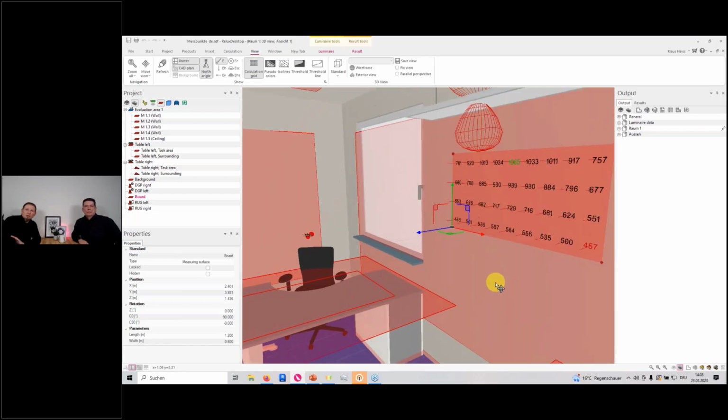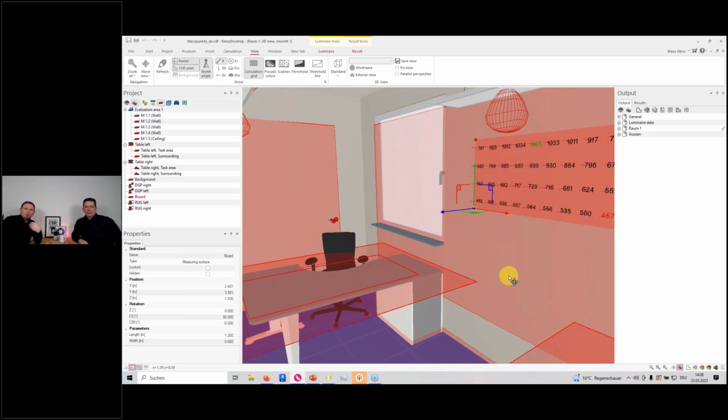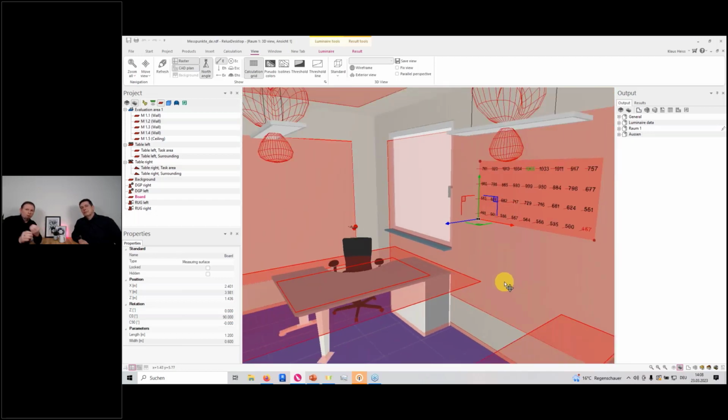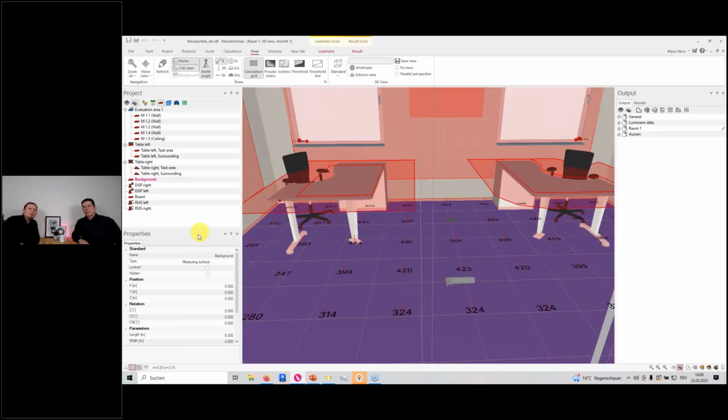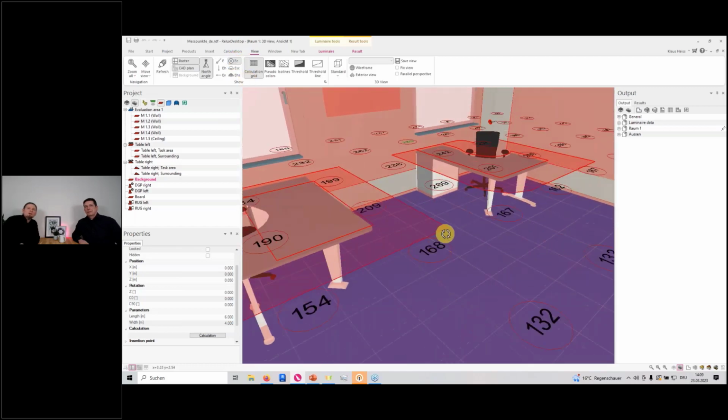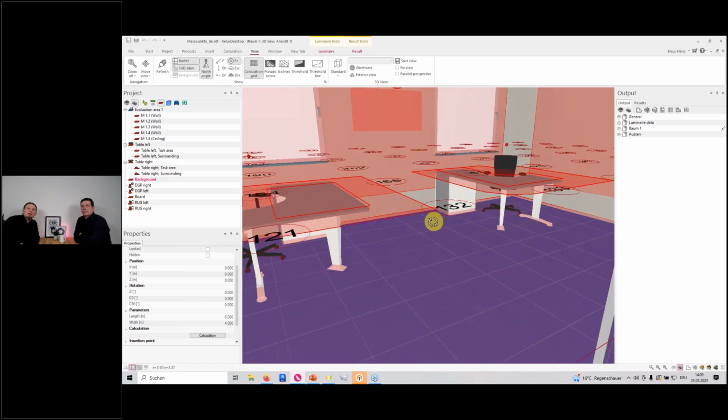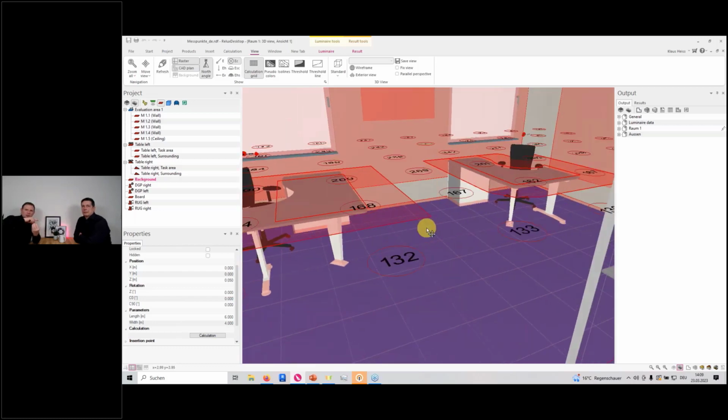There are also some measuring points on the grid scale which are not just from one direction. We can also collect the illuminance from multiple directions. For example, we also have the cylindrical values, which are reflected in the 12464 standard. I have one sample here on this background area. This means on these small circles, we calculated the light from all directions on a cylinder.